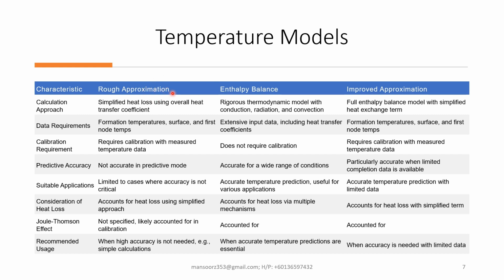Furthermore, the enthalpy balance always commences from known initial reservoir conditions and subsequently iterates to align with the user provided wellhead data, pressure and temperature. This often necessitates multiple iterations for each flow rate to attain convergence. These factors collectively elucidate why advanced thermal calculations employing a fully compositional fluid description tend to have longer computation times.